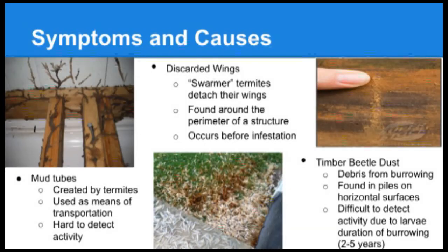They tend to feed on the interior as well as the exterior of timber members within structures, and they usually work their way from the bottom to the top of a structure. But sometimes some species of termites are able to colonize various places of a structure, allowing them to attack the structure from various points. And here are some of the symptoms of insect and bug infestation.